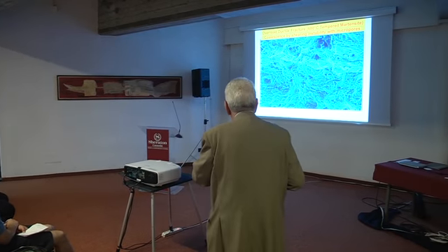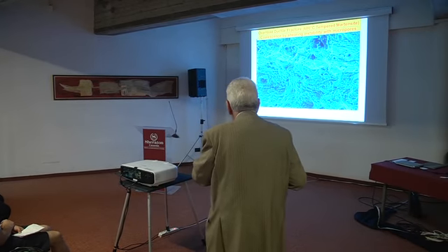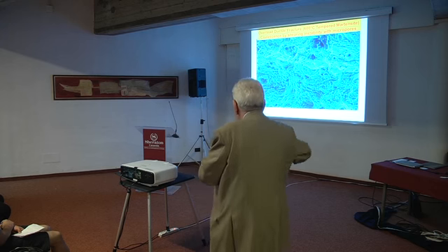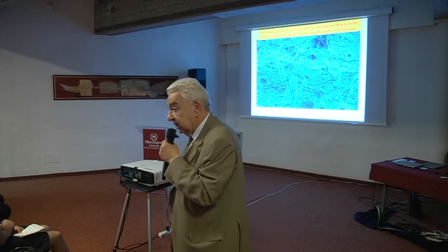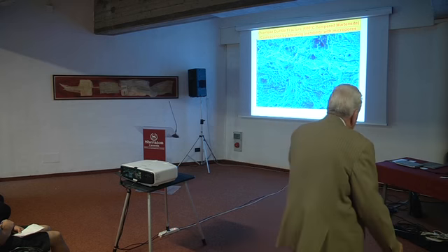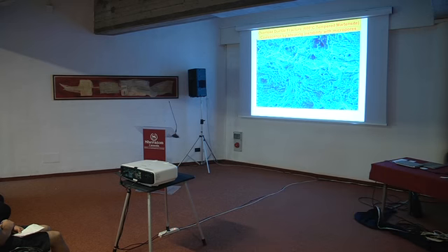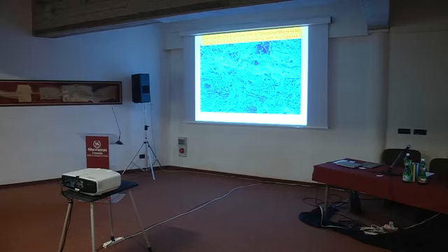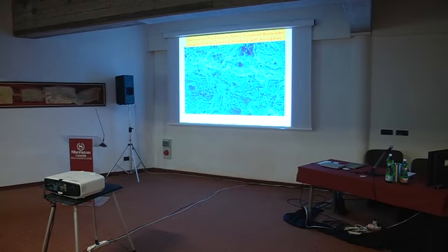And these are nucleating around carbides. And then you are increasing here the fracture toughness. You are taking it to close to 100 megapascal square root of a meter.